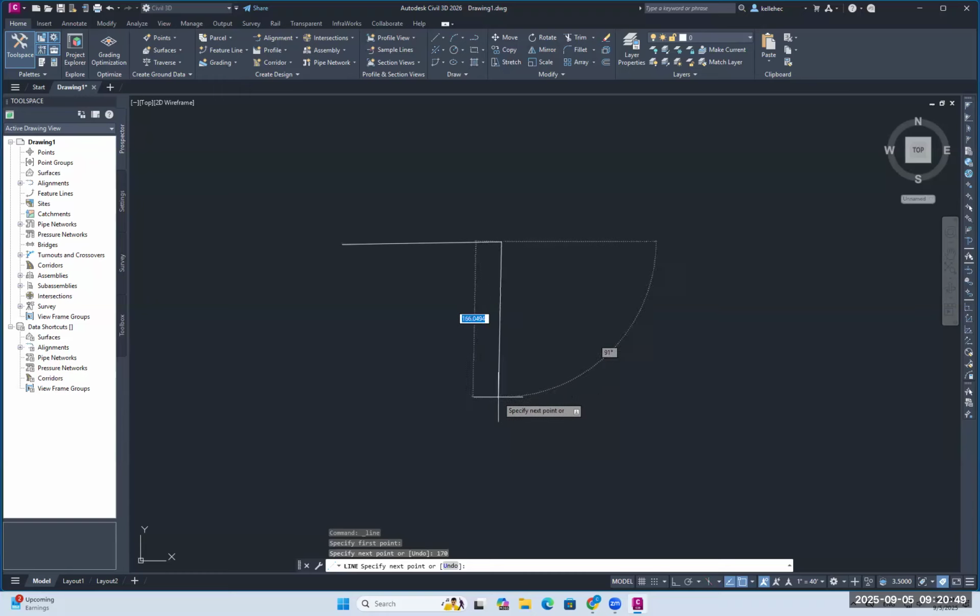Now, I want to come down this way. I'm actually going to click on ortho, and look at what happens. It restricts me to those 90 degrees, which I think is actually pretty cool. And you can see my first line wasn't perfectly straight. That's okay. You can fix it if you care that much. I am down for whatever you want to do with this. So I've got 50 on that dimension. I've got 60 on that dimension. I've got 12. I've got 50. I've got 12.